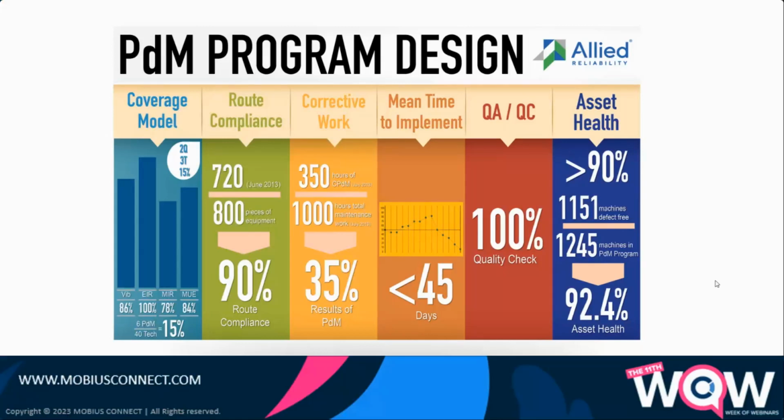Then you go into performance of the overall program, route compliance. Route compliance targets of greater than 90%. Condition monitoring technologies won't do you any good if you're not consistently meeting your route compliance needs and your inspection frequencies to tell you the health of the asset and the failure modes as well. Route compliance is calculated by the total number of assets that are on route divided by the total pieces of equipment. The 720 is the total number of assets that were inspected divided by the total number of pieces in your condition monitoring program. So in this case, 720 divided by 800, 90%. So 90% is your minimum target.